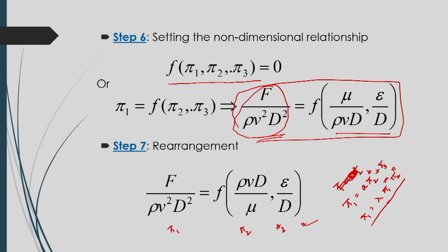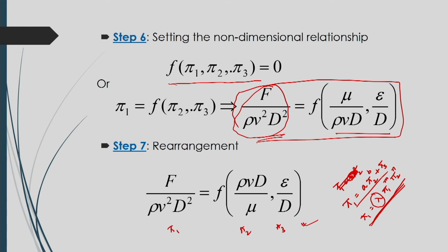So, either way, that depends on your experimental data, how this flow resistance will be changing with respect to variables. If you have different data based on changing of independent variables and its result on the dependent variables, then you have to fit this equation, either of these equations, with that experimental data. Then you can have the values of m, n and lambda, or here a, b and some c value.